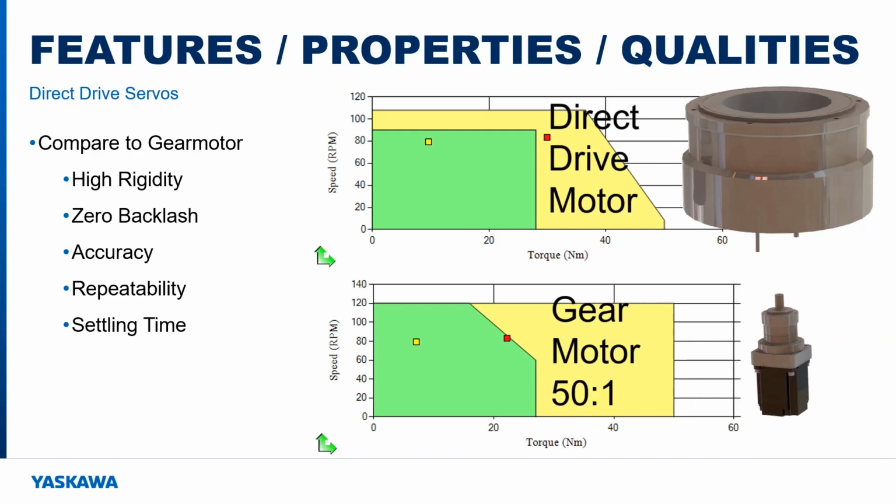Both motors can solve this application, but even the best gearbox adds a level of compliance and backlash. For this reason, the direct drive motor will accomplish the task with higher accuracy, better repeatability, and lower settling time. I'll explain more about this in a few minutes.